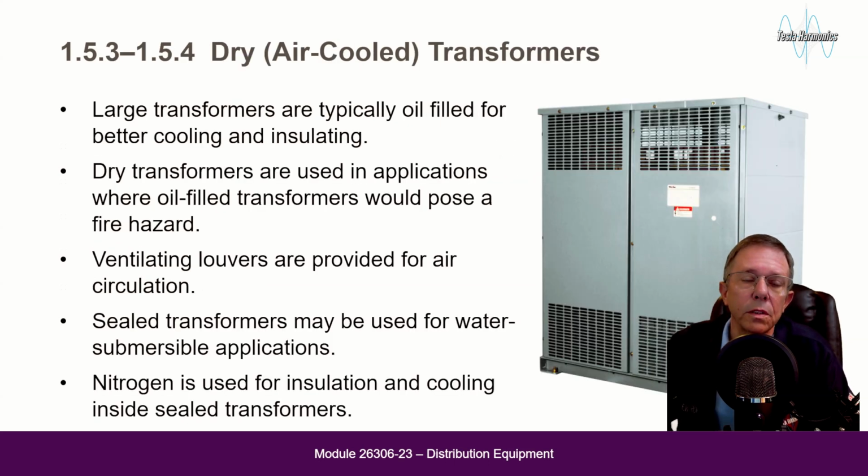Dry transformers. Large transformers are typically oil-filled for better cooling and insulating. Dry transformers are used in applications where oil-filled transformers would pose a fire hazard. Ventilating louvers are provided for air circulation. Sealed transformers may be used for water submersible applications, and nitrogen is used for insulation and cooling inside sealed transformers.